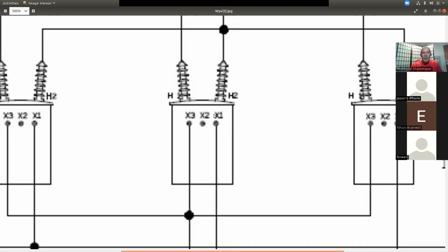If you had the lid open and you took the leads off, you can actually see a stamped in letter on the lead. To convert, and how many bushings are they using here? 1 or 2? 2. Just 2. Okay. To convert this transformer to 120 only, it's a very simple process. I've got A, B, C, and D. That's the way it comes from the factory.